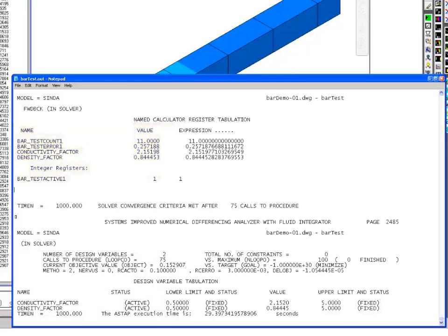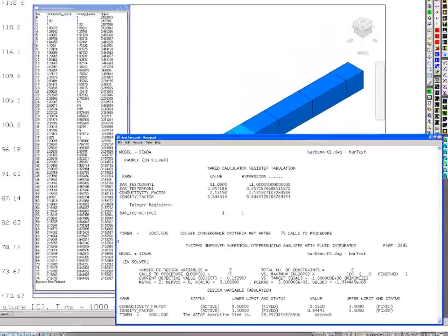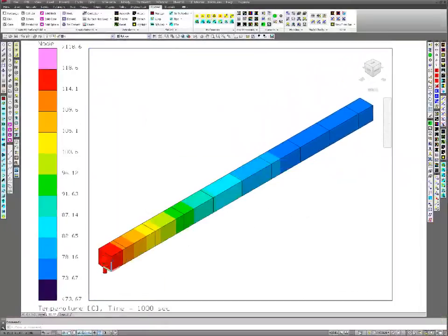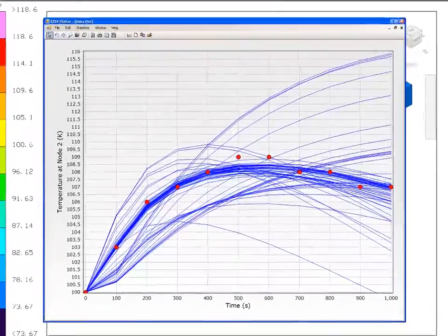I will leave you to explore what the uses of the count and the error variable are in the TD manual. The active flag here, it is an integer register, is one that I mentioned in the video. It's the one that you would set to be 1 or 0 if you wanted to turn on or off the activity of the data logger. So in other words, you could set it to 0 in logic or expressions to turn off the data logger, say if you wanted to do some preparatory calculations. Otherwise, the final results for the run are best summarized here.